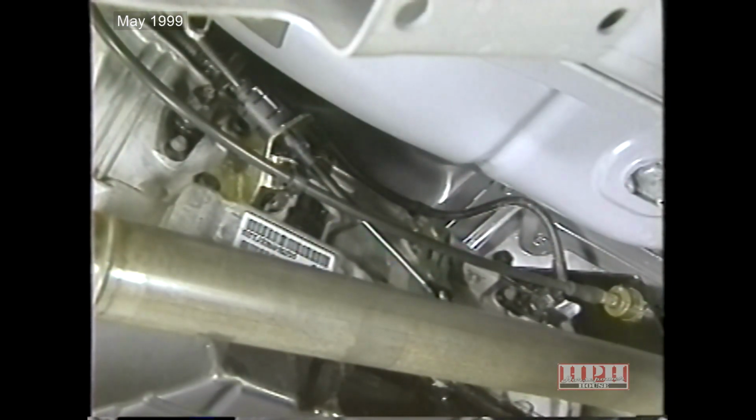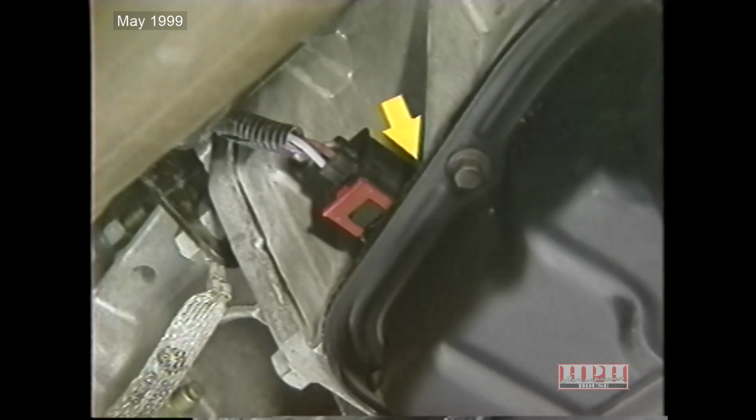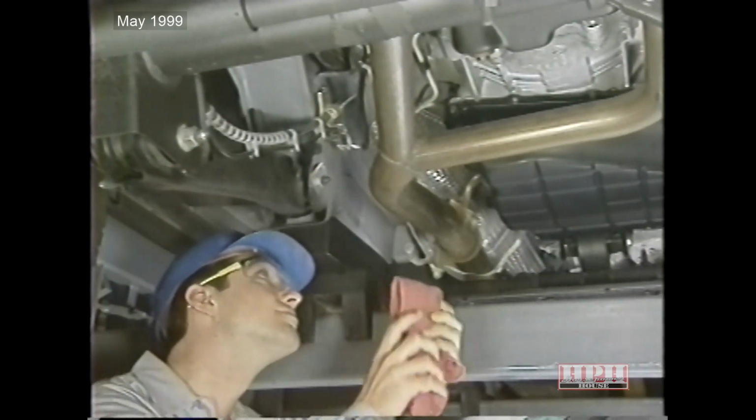As with engines, your checkpoints will vary according to vehicle and transmission usage. On the left side of the transmission, check for leaks around the input speed sensor, the output speed sensor, the manual lever shaft, and the 23-way connector. On the right side of the transmission, check cooler outlet and inlet ports and lines. Check the area around the line pressure sensor for fluid, and check for fluid around the fill tube connection at the case.